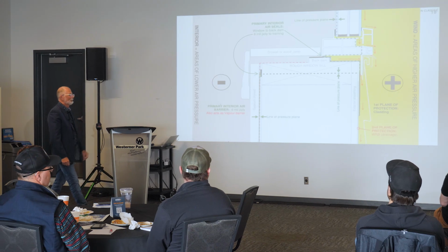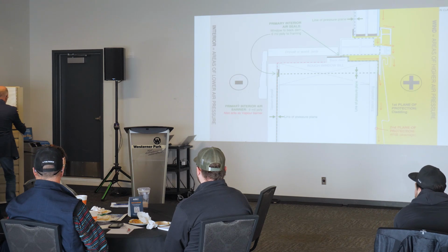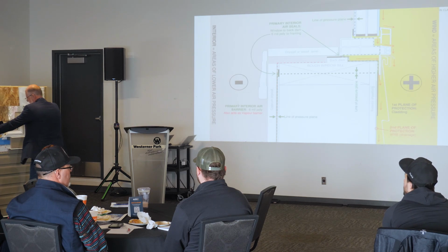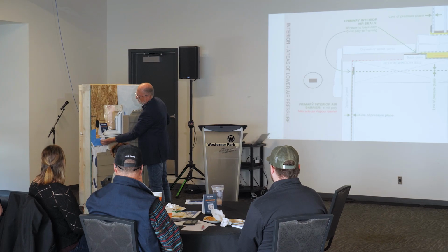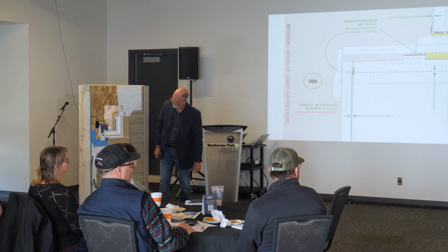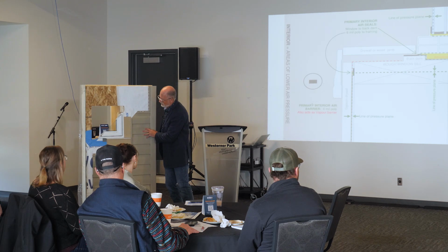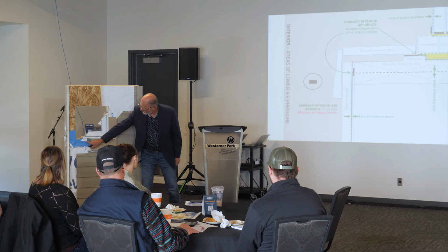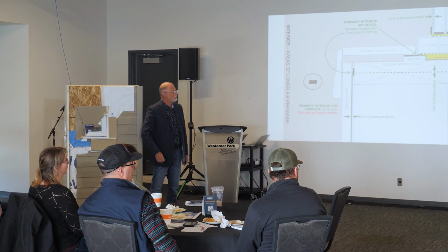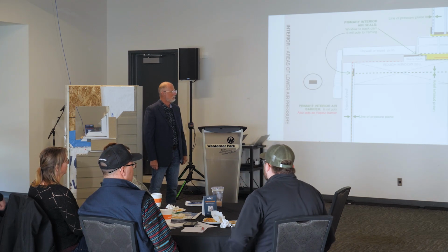So the wall assembly that we rolled up here that's behind Darrell has the flange on the bottom. If you take a close look at that, you'll see the realities of installing the materials that go behind the flange itself, the frequency of the nailing. There may be points along that flange that are sealed, but there will be plenty of points that are not, that have a microscopic channel, that have the ability to release that water, exactly as Darrell was describing. And as long as that's not taped over, we've found that you're going to be good, right? That's the key step, to leave that open so that those microscopic drainage planes can do their job.